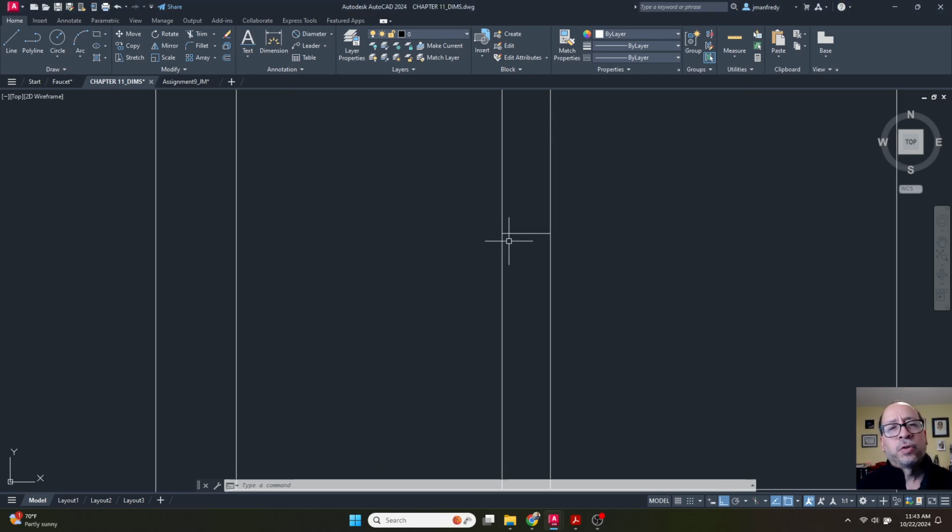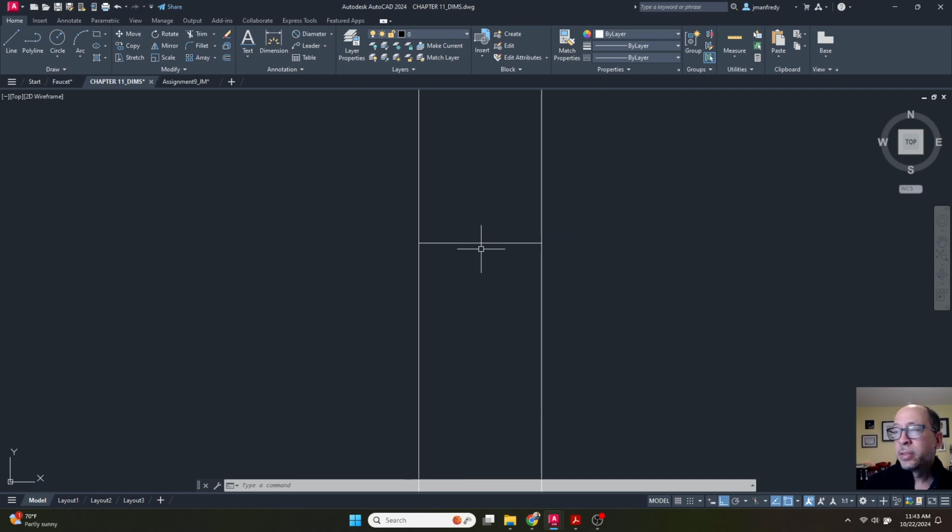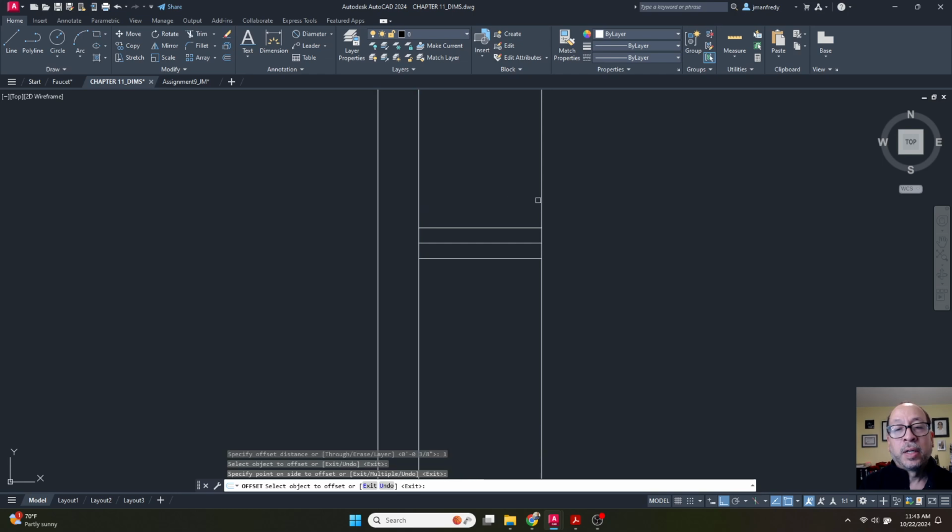As far as the latch is concerned, they actually drew it in another place in the set of drawings, and they measure here. They state that this thing is 3/4 inch thick, so let's go 3/8 of an inch above and below the center line. It's 5 inches tall. It's 5 inches long, so that means I need to offset this another inch because it needs to be 1 inch longer, and I'm going to fillet these edges here.